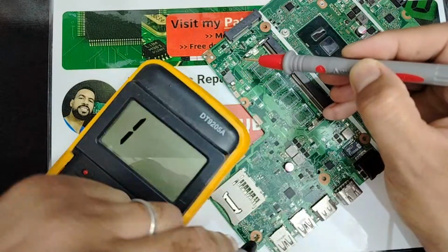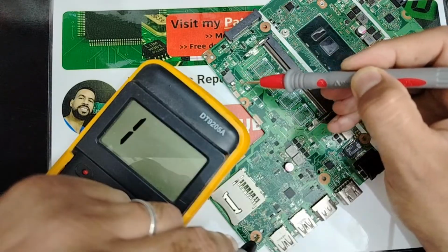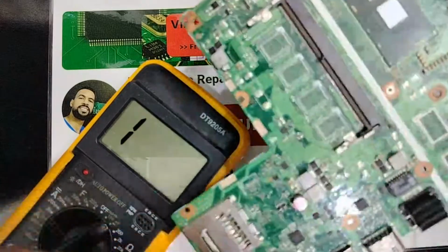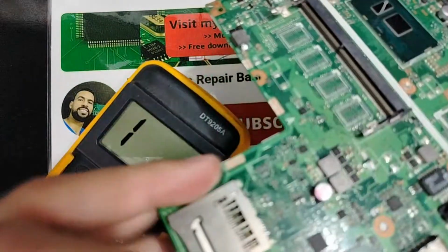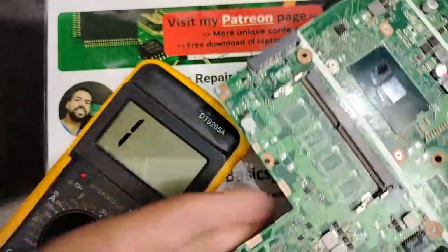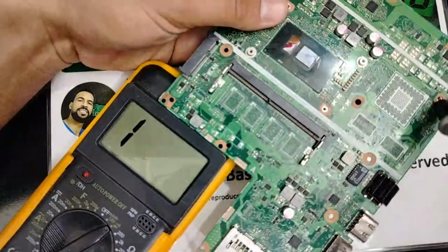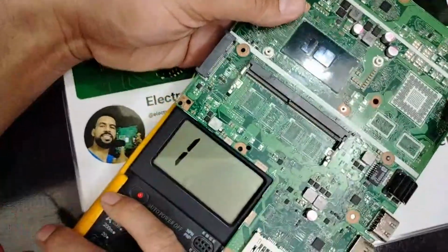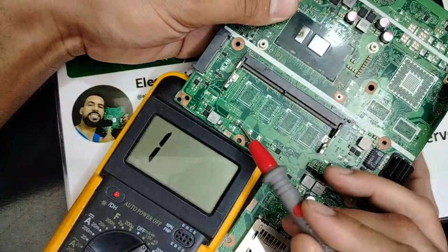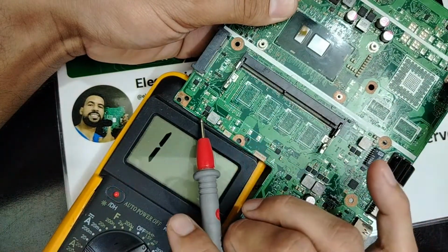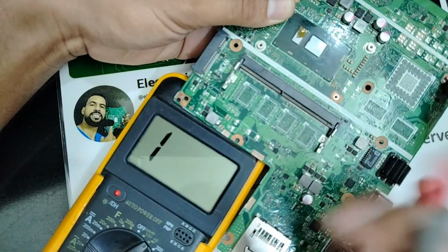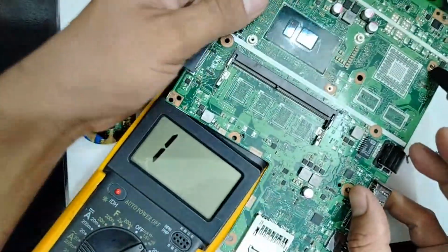And basically, this circuit contains the ceramic capacitors in the output. I don't know if you see it clearly or not. Maybe like this will be good. Okay, my friend, here we have a short in this circuit. In this inductor, we have 0 on both sides, meaning this is a short, okay? This is a clear short.